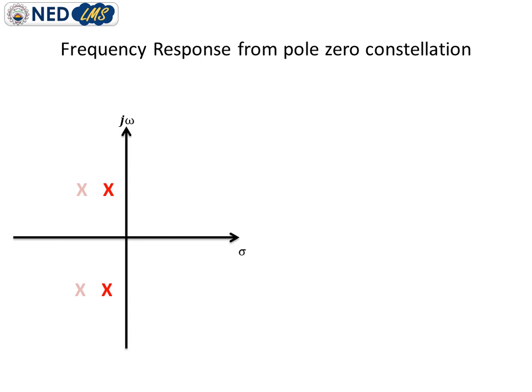Whatever the effect for shifting valid for poles, the same effect is valid for zeros. We are just trying to find out what if I shift the roots of this system towards the y-axis, or vice versa, away from the y-axis.